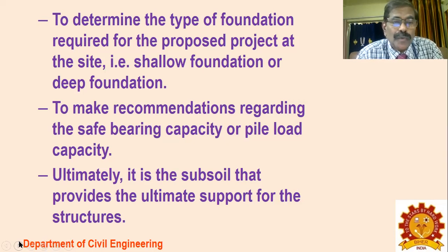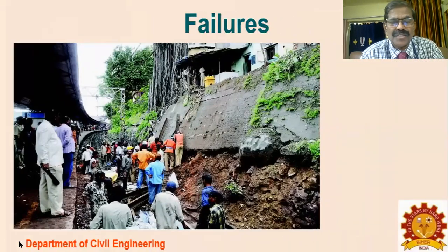So you decide about the foundation, what type of foundation, either the deep foundation or a shallow foundation. It may be a shallow foundation, an isolated footing, or it may be a raft foundation. If the bearing capacity is good and column spacings are very near, the raft foundation may be ideally suited for the structure. Or if it is concentrated heavy loads and your subsoil has very low bearing capacity, then you have to go for deep foundations like pile foundations. That decision you need to take only if you have done the field explorations and soil explorations.